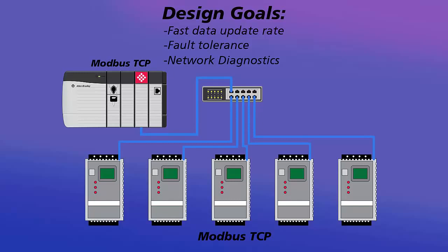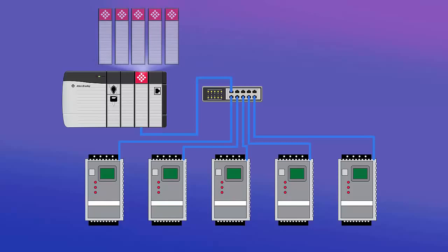The ideal situation here would be to use a communication module that supports multiple clients, one talking to each of the servers. This will ensure faster communications by giving each drive a dedicated connection to a Modbus TCP IP client. Commands can be sent to all 5 drives by separate client connections instead of cycling through each drive one at a time.